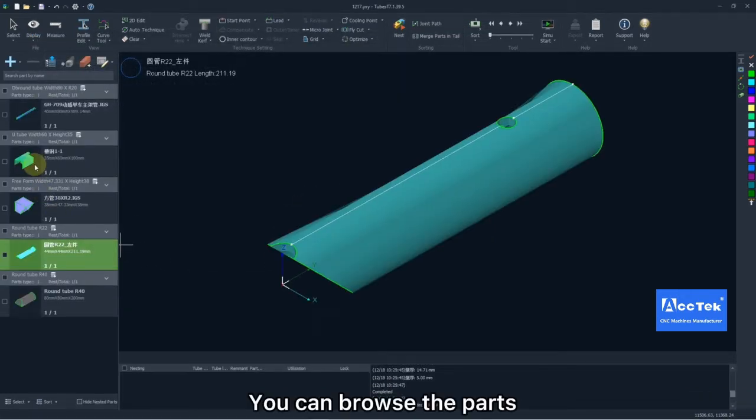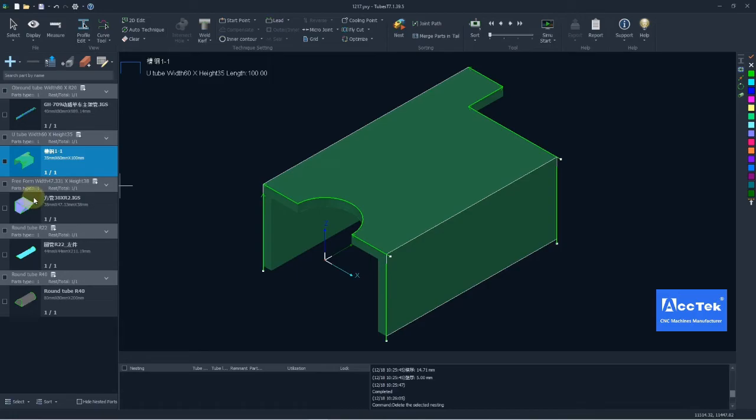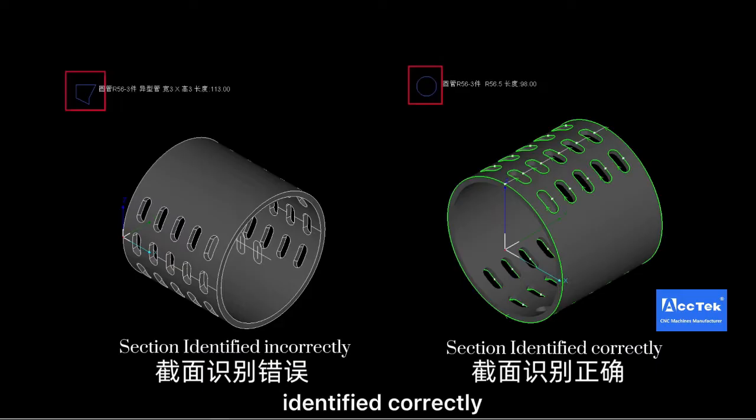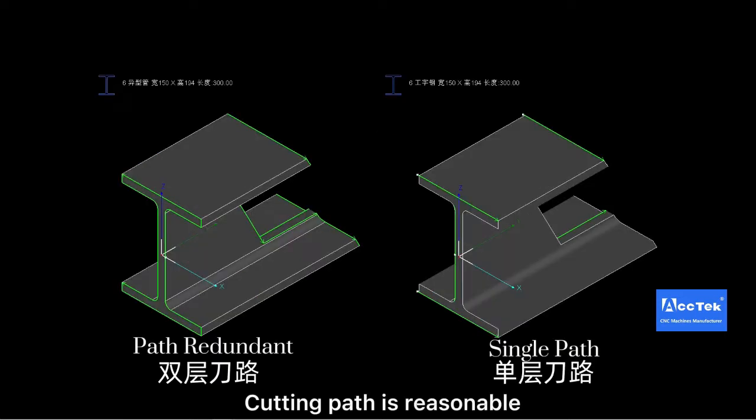You can browse the parts respectively to check if they are imported correctly. To ensure that, you need to get 3 things covered. The section is identified correctly. Extrusion direction is along with y-axis. Cutting path is reasonable. Generally, you need to check if there's no redundant cutting path.